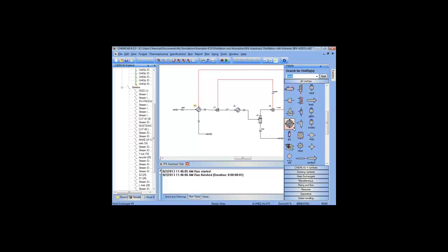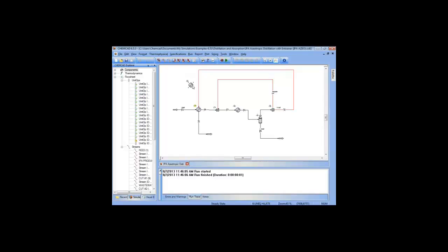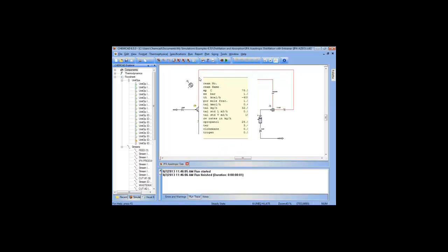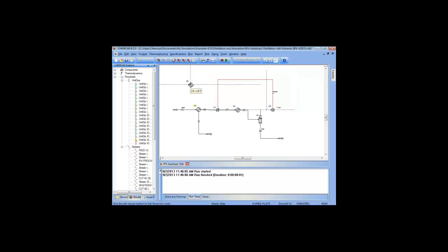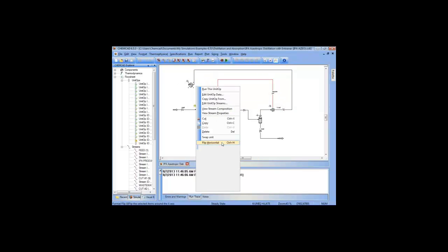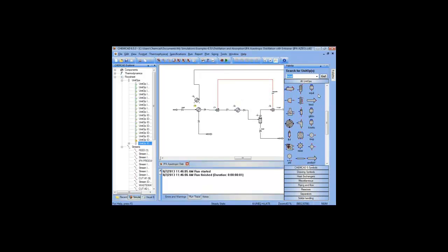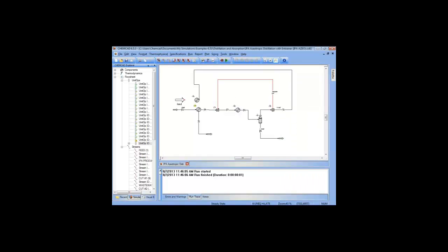So that would make it hard for me to troubleshoot what went wrong. How did I specify this in a difficult way? So again, if I'm doing a thermal recycle, I'll start the flow sheet like this. I'll have two separate heat exchangers that I put close to each other. I'll have my stream coming back to recirculate into a heat exchanger, and I'll put it close, and I'll have a new feed, which is my guess for what's in the recycle, and I'll have a new product.